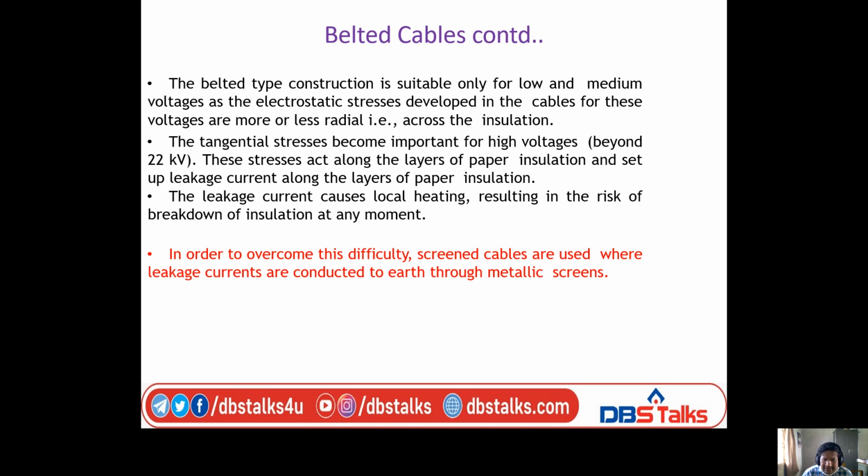The tangential stresses become important for high voltages. These stresses act along the layers of paper insulation and set up a leakage current along the layers of paper insulation. This leakage current causes local heating, resulting in the risk of breakdown of insulation.